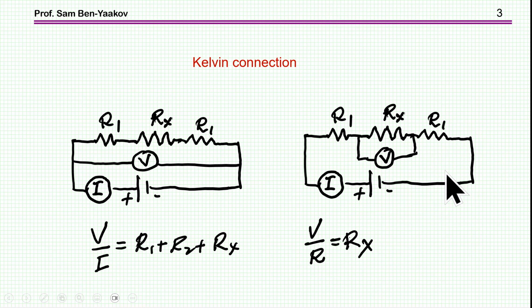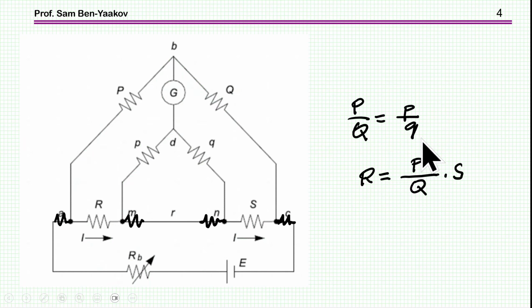Okay? So a current sensing resistor might have in fact four terminals, two for the current passing through it, and then two for sensing the voltage. Now, the Kelvin connection comes from the Kelvin bridge, which is a rather involved configuration, which is meant to measure by a bridge type of testing the resistance of an unknown resistance, if you know the reference resistance, by a bridge which is sort of balanced.